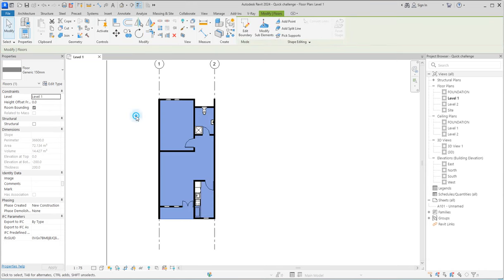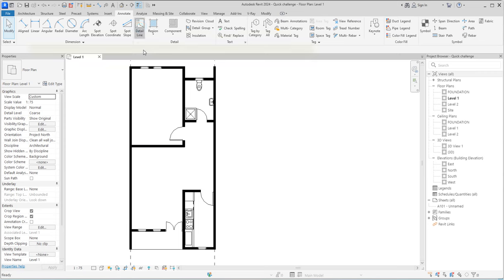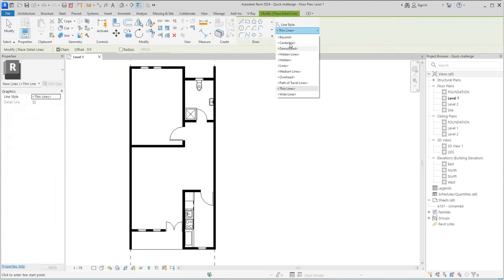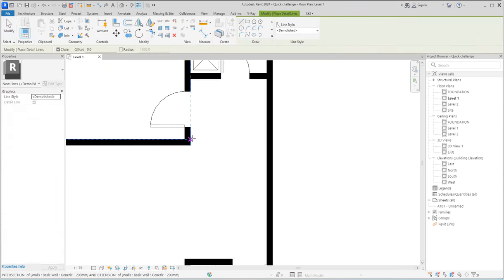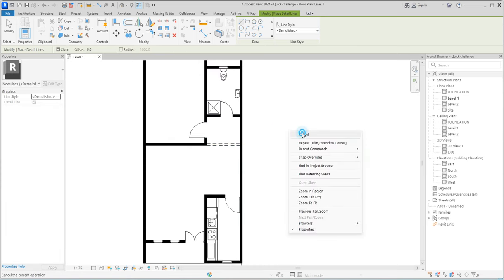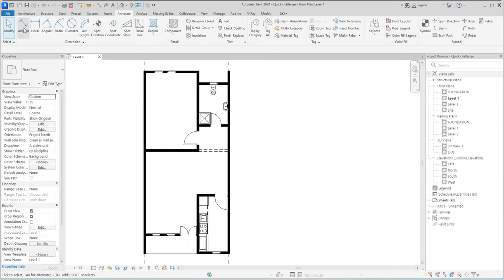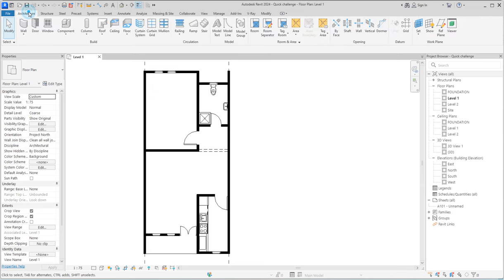The next thing is I want to put furniture here. This is the dining area. So for me to represent an archway here, I need to use annotate to create the archway. Click on detail, then you select the line by clicking on demolish. At the demolish level, you do this one, paste it. The same thing, you paste it on. So this one represents that there is an archway to this. So whenever they want to put curtain and whatever they want to do during interior aspects, you can do that successfully.